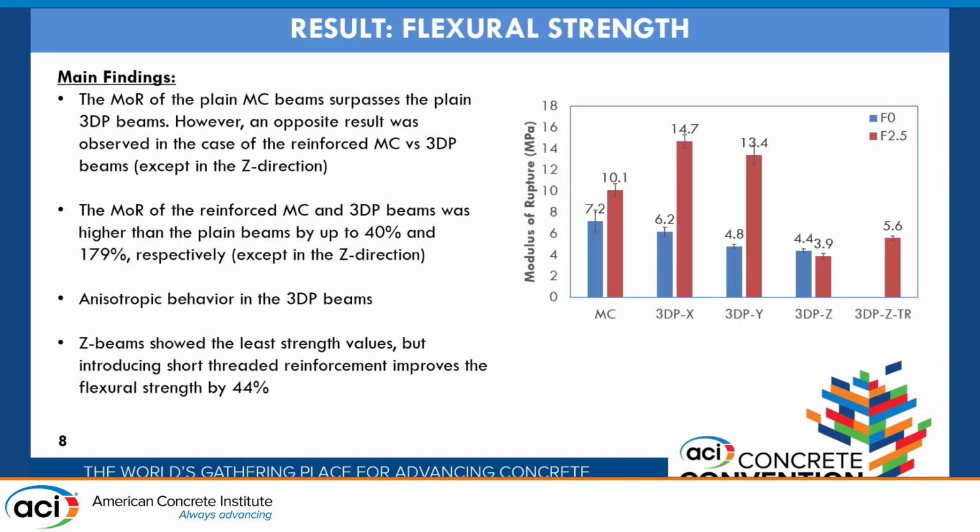And then in terms of the flexural strength, we tested both the mold cast and also the 3D printed specimens in different loading directions. And our results show that in the case of the plain mixtures, the mold cast specimen actually outperformed the 3D printed specimen by up to 50%. And of course, this is due to the presence of multiple interfaces in the 3D printed specimen as opposed to the monolithic mold cast specimen.